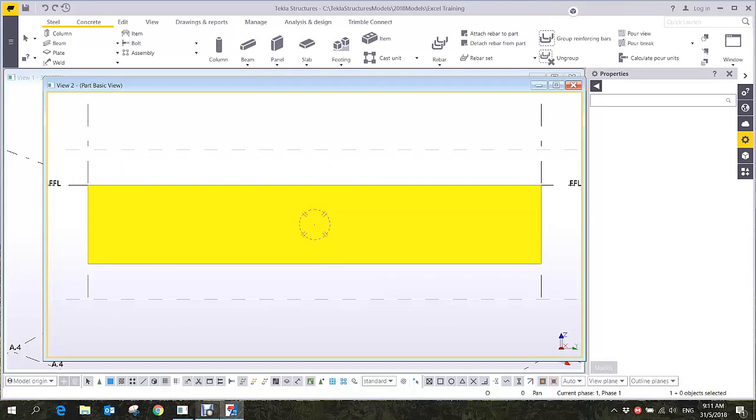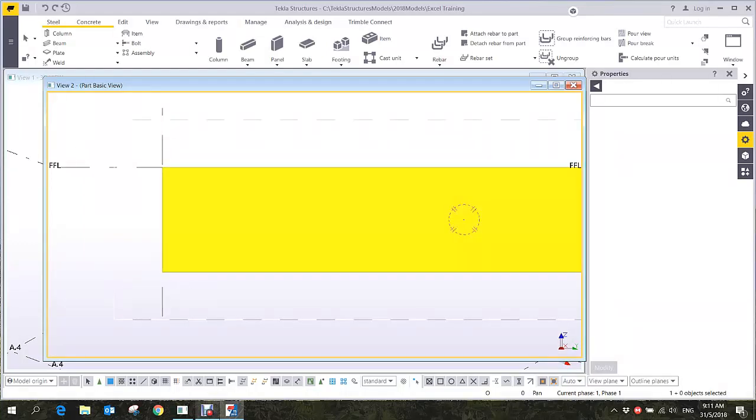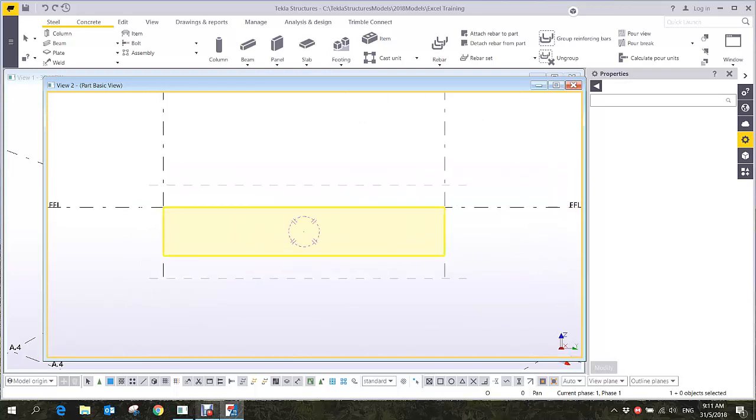So kindly add this 350. So 350 from 350. Okay, let me just show you here. So to add the cuts here, because in this case, I want to cut 350 millimeters from the end, right? So we don't have the reference yet unless we add the construction point or construction line. So at the moment, we're going to create a construction point.